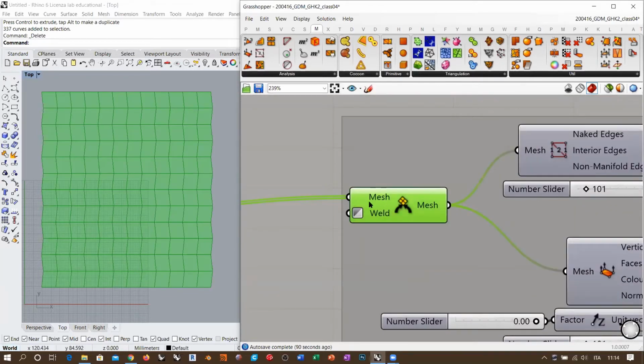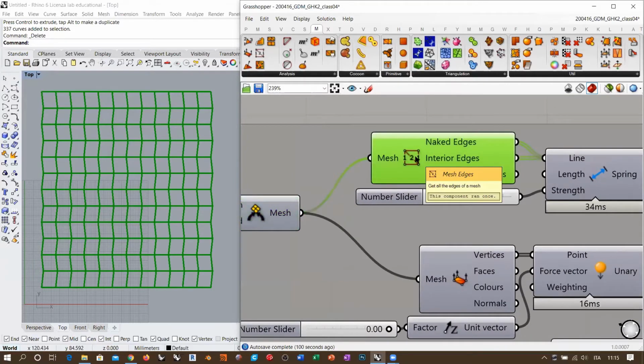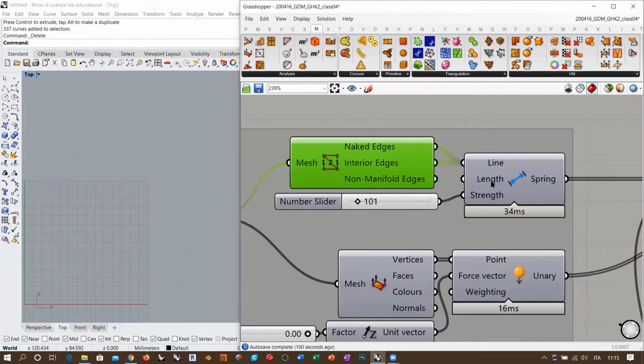and join all the meshes together in order to have one single mesh with 144 faces, while the triangular mesh has 288 faces total. So I'm taking the quad mesh and extracting all the edges and giving elastic property to those edges in order for them to remain undeformed during the simulation. Okay, very rigid, very stiff springs.